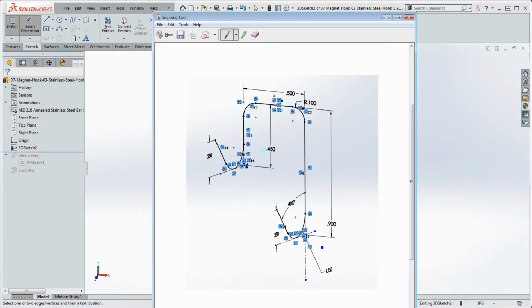But the next thing we want to do is put in some sketch geometry and go down here 0.9 inches down over here. And we're going to put in a sketch geometry down here, which is going to be, both of them are going to be center lines. And we're going to put a point down here too, if you can see where the cursor is. And we're going to go ahead and apply dimensions in here.